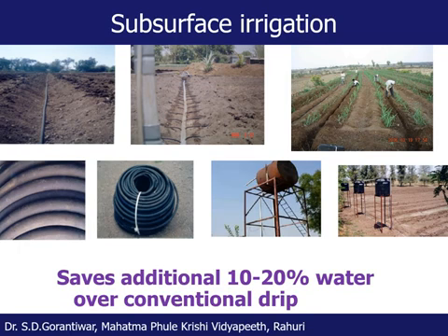The purpose is that in the subsurface irrigation method, as per its philosophy, water is to be maintained beneath the soil surface all the time. So in this porous pipe subsurface irrigation as well, water is to be maintained in the porous pipe all the time. When the plant root takes water from the soil root zone, what happens is that inside the porous pipe water is maintained at full potential, and in the root zone initially the water is not at full potential. Therefore water will seep from the porous pipe into the root zone.